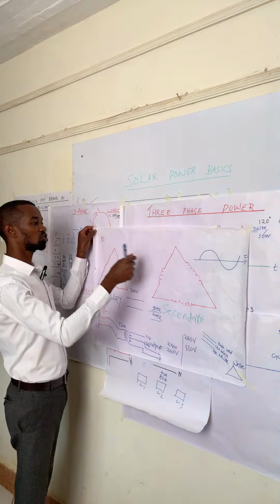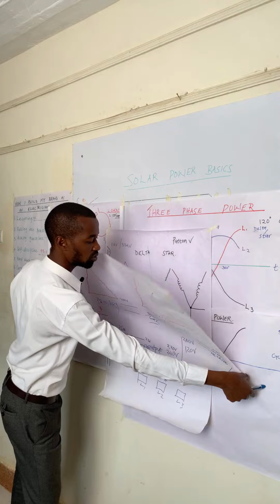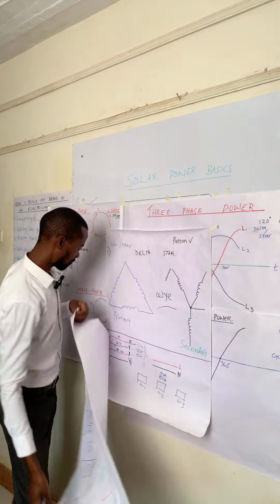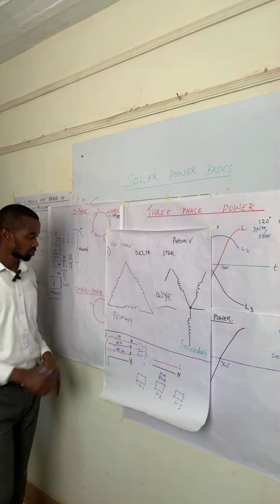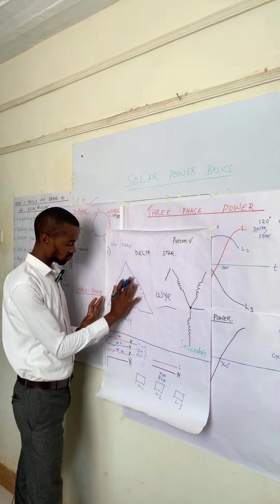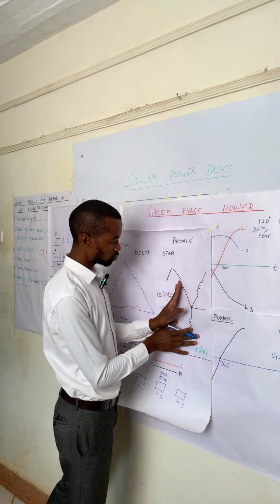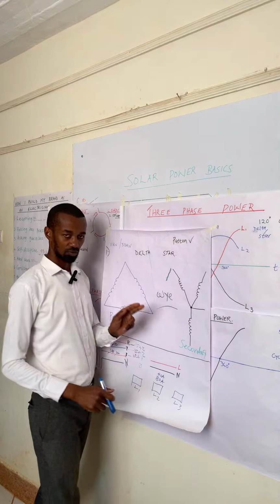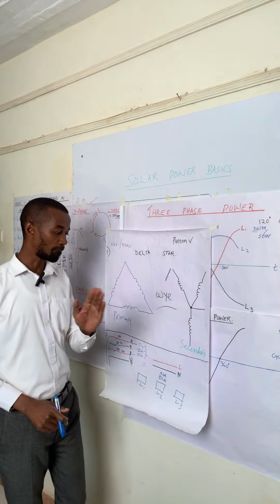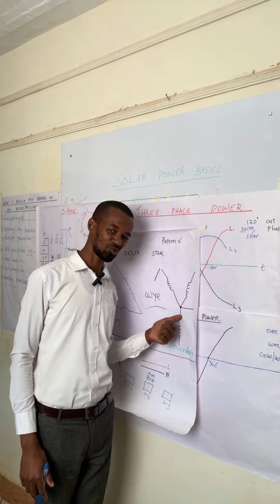From the delta connection, we will achieve on the secondary a star connection, forming a delta star connection, which is right here. So the three conductors will be fed to the primary of the three-phase transformer, and then on the output where we have the Y connection, we will have the three phases, which is red phase, yellow phase, blue phase, and something extra which is very important, the neutral.